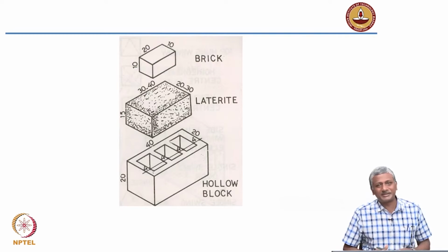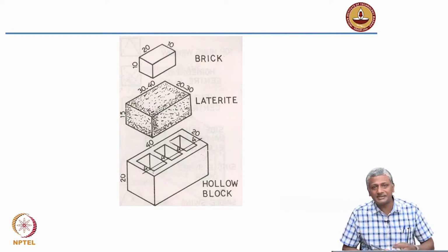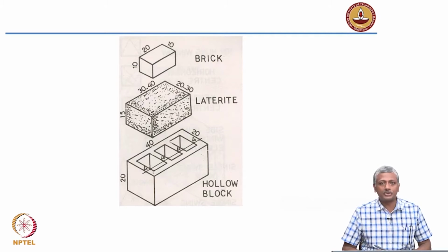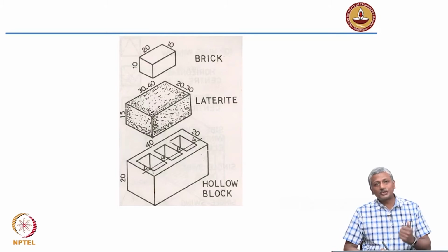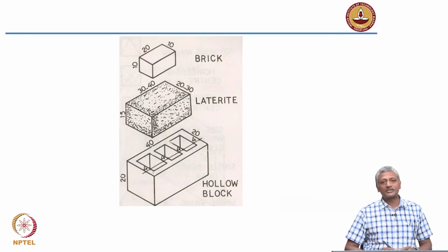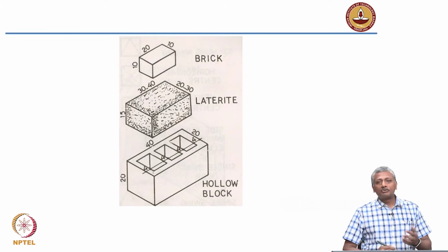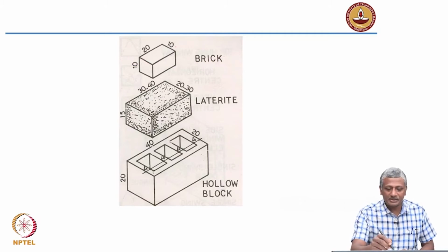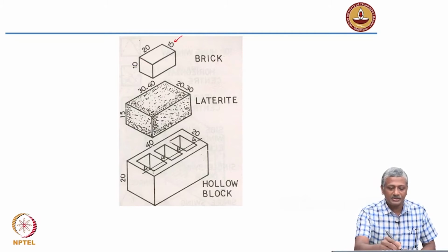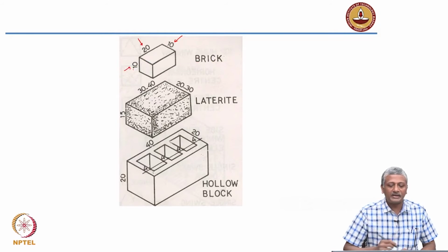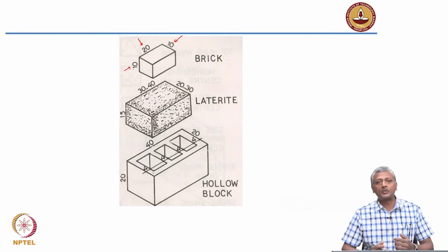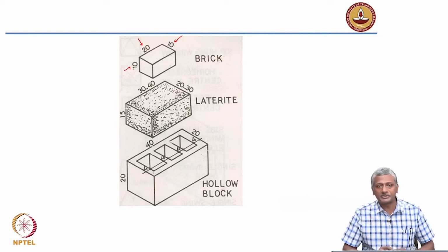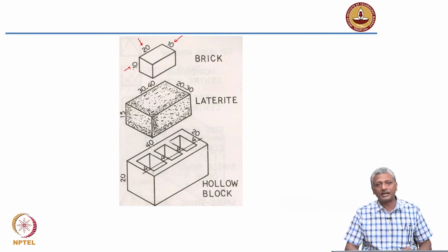Now, just to give you some example of typical sizes, you may have seen these stones and bricks lying around on job sites. Some of you may have lifted these also. But if I ask you the weight of a brick, many of you would probably think that it's about a few 100 grams. Okay? But you don't realize that with this size, this is a typical modular size of a brick, 10 centimeters by 20 centimeters by 10 centimeters. This is a modular size. This is what we use for design and drawing purposes. But the true size is quite different. I'll talk about that a little bit later.